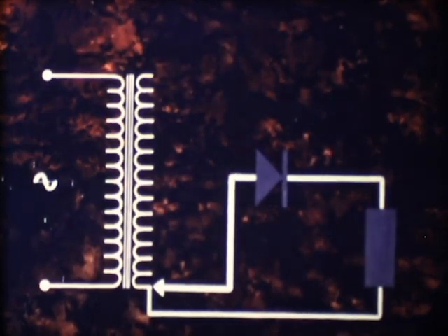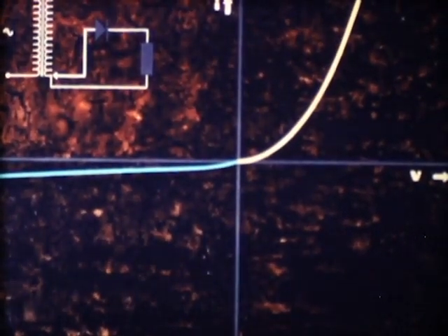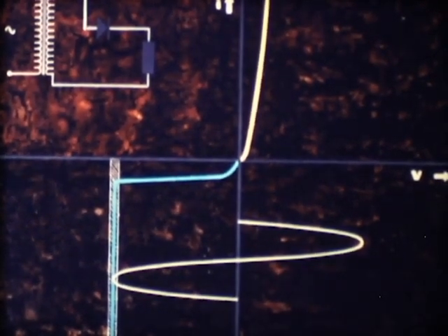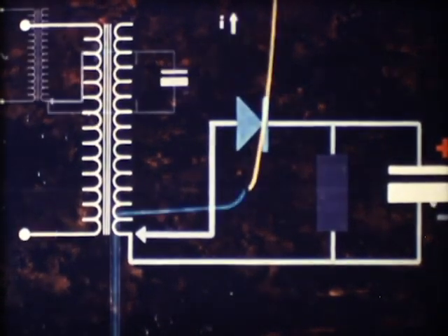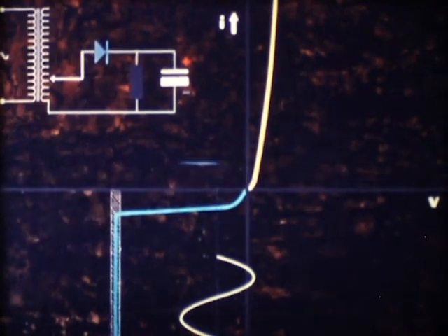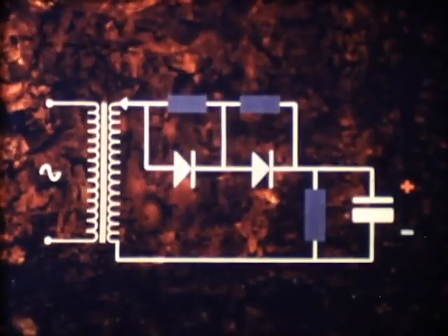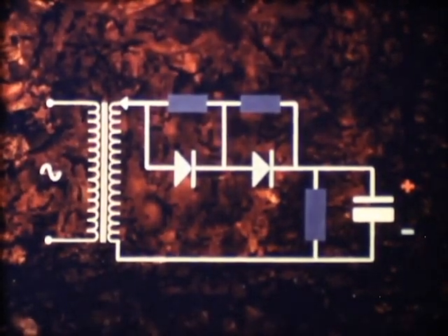For a supply circuit having a resistive load, the maximum permissible value of alternating voltage to be applied is determined by the breakdown point of the particular diode characteristic. Shunting the resistor by a large capacitor will cause the working point to shift, with the result that the applied voltage must be reduced to half its previous value. Higher voltages can be rectified by connecting 2 or more diodes in series, so that the voltage across each diode is kept within the permissible limits.